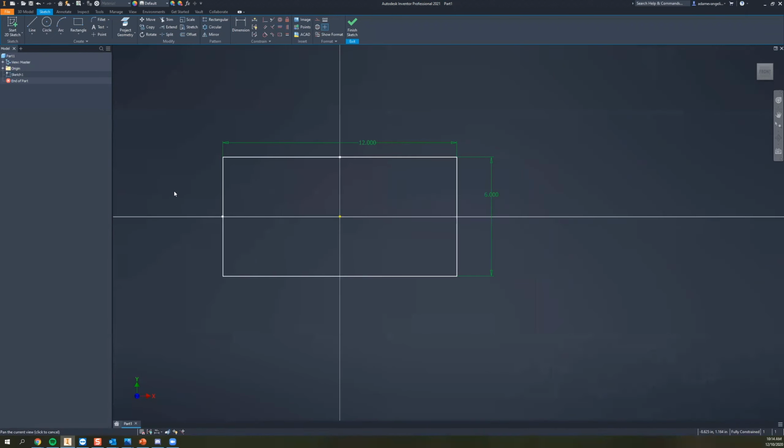Beautiful, okay. And then we're going to place some work points here that will allow us to center these along the center over here. I'm going to do a little cross beam over here, make it a construction line, add some points. 1, 2, 3, 4. Okay. And we're just going to make this a spacing. Let's see. So that's going to be 3 inches to make it even, I believe. So we'll call this spacing is equal to 3 inches.